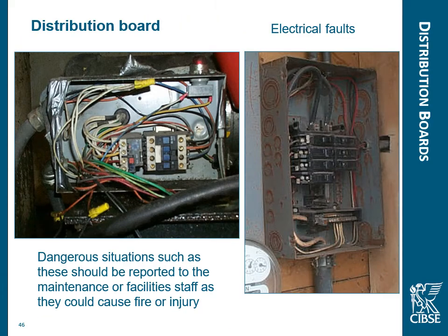Anything that doesn't look right on an electrical circuit, it's worth reporting that to the electrical engineer on site. We quite often find that lids get missing and lids are off circuit breaker boards and stuff like that because the screws get lost. So make sure that these lids are replaced, because potentially in here we could get overheating, and we don't want that causing fires outside.